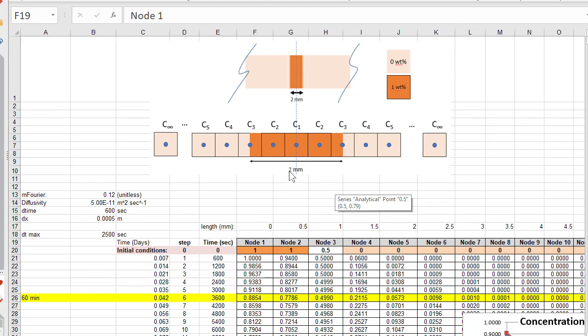All right, now remember, with our semi-infinite solution, what that really means is that when we get to the time step that we're interested in, if I look at these columns out here on the right, they're still going to have a concentration of 0. And I want a few columns out here to have that value. That suggests that my sample is thick enough, I have enough columns, that this diffusion process hasn't reached that far into the sample. So we'll take a look at that in a second as well.